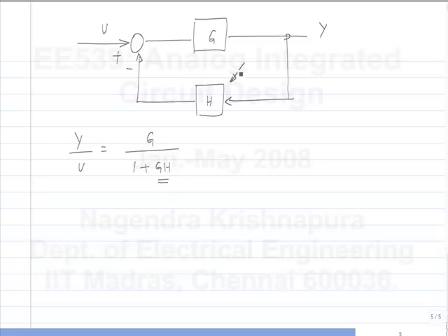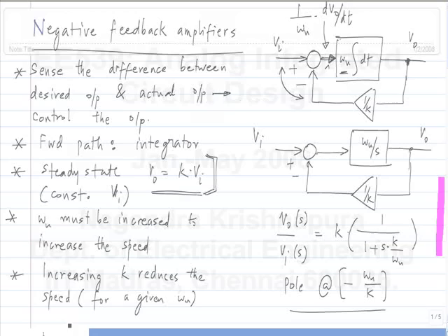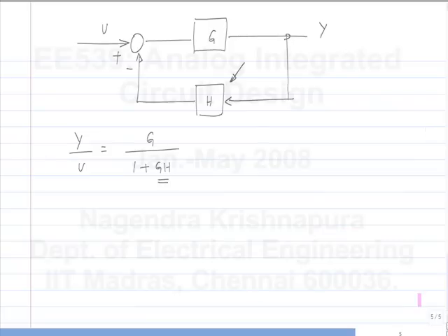So now, under certain circumstances, the gain will be a function only of the feedback fraction, just like we saw before. So in our feedback system also, the steady state gain is dependent only on K. It's not really dependent on omega u. So maybe you make two different amplifiers and they have different omega u's. You can't control it very well, but you can control the attenuator very well. So the gain will still be K, and will not be primarily affected by omega u at all. So that's the motivation for making feedback systems.